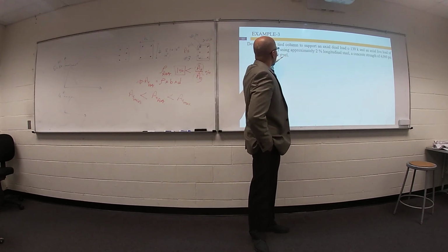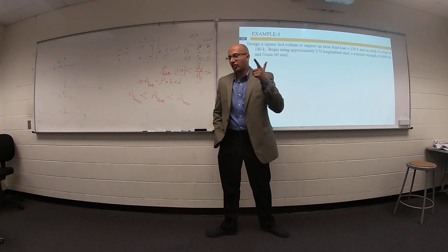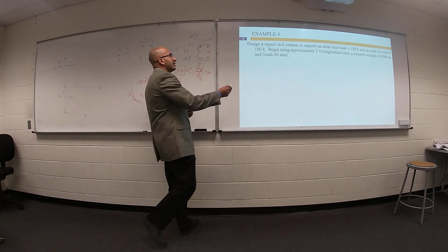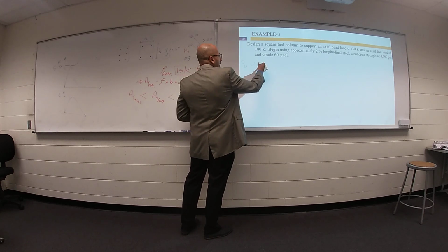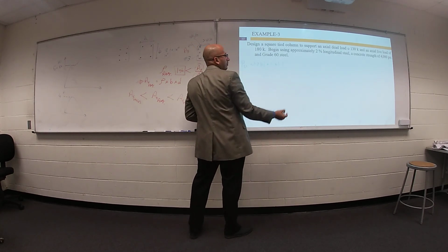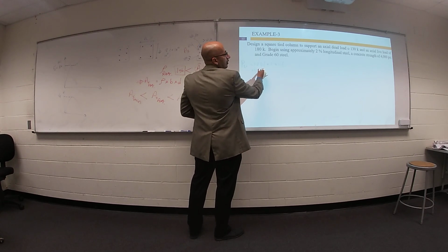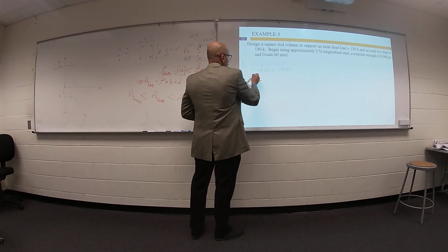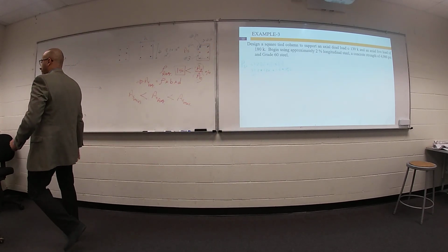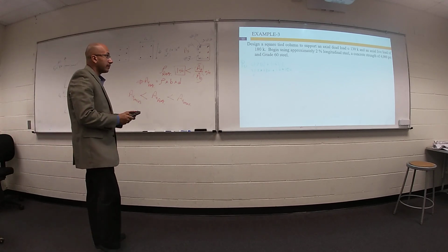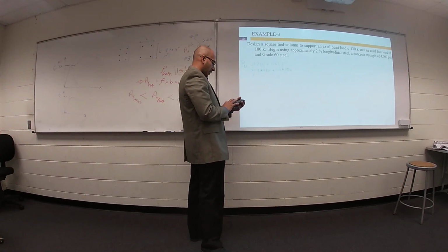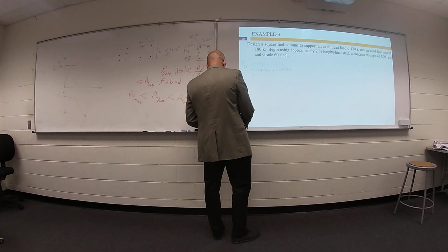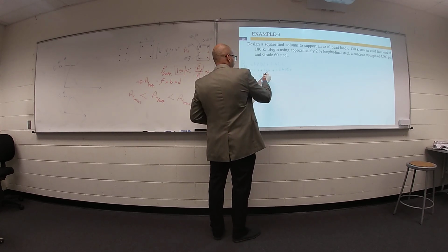There is a hint here: steel reinforcement not given, cross section not given, nothing is given. The only thing given from structural analysis is your P ultimate, which is 1.2 dead load plus 1.6 live load. 1.2 times 130 plus 1.6 times 180.